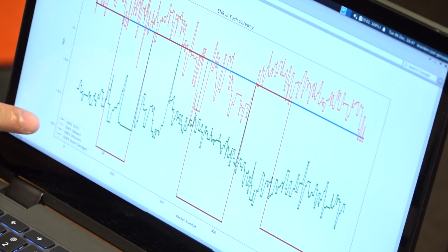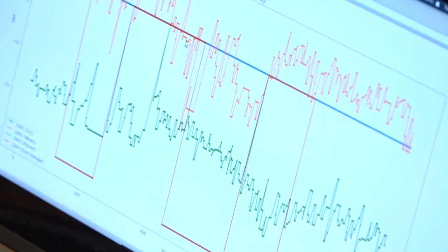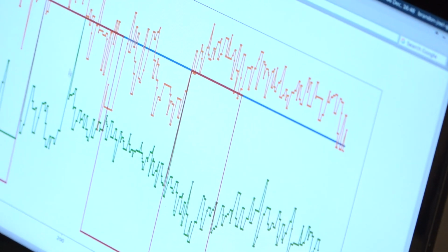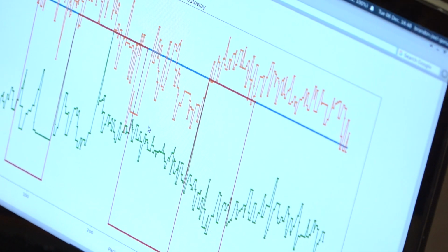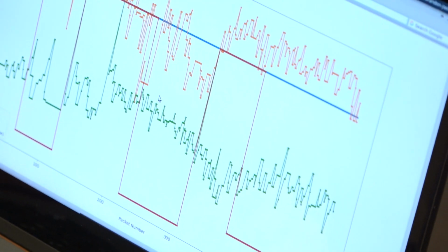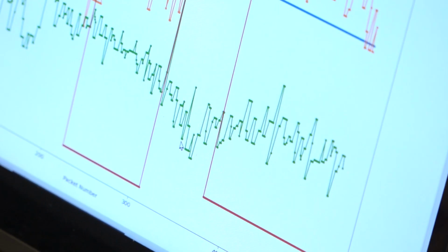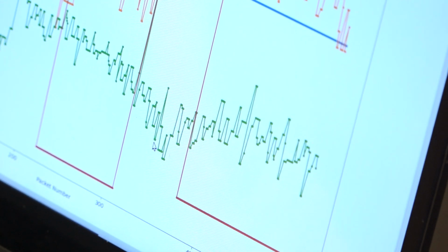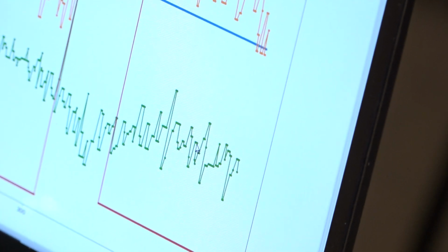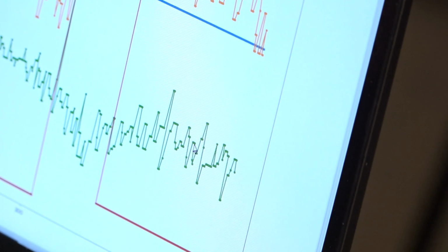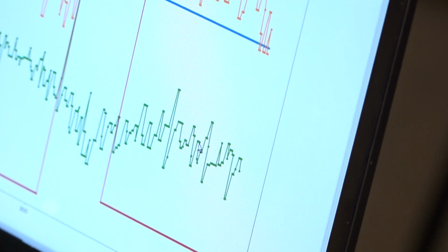You can see it's dipping towards -20. What's more interesting is what we're getting at Posner Hall in green and at Wean in yellow. We can see the SNR that we're getting. Around this point is where we turned on the interferer, and we can see the SNR values dip. We can see a dip once the interferer is turned on, and then once we disconnect the interferer, we see the SNR values go back up, because that's what we expect when we turn on an interferer. It's interfering with the signal that's being propagated, and then once we remove the interferer, we see the signal-to-noise ratio improve.